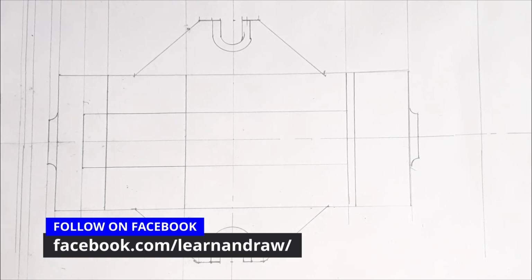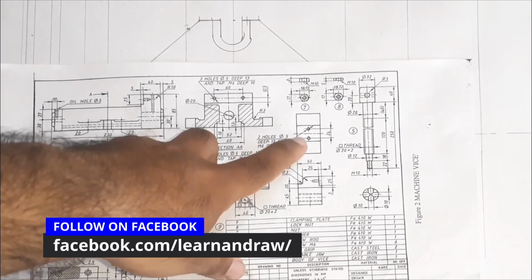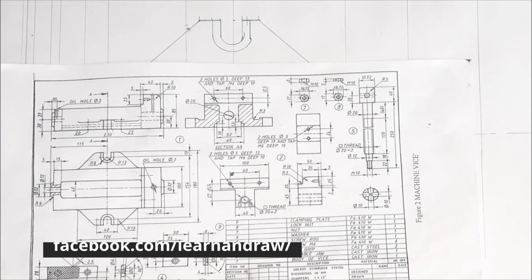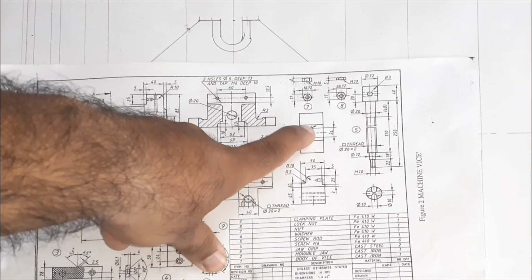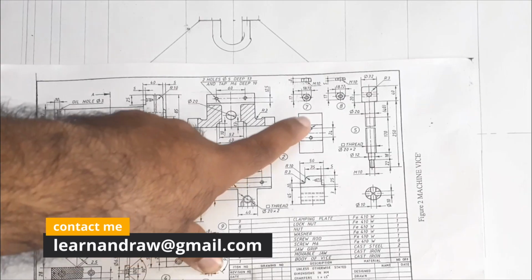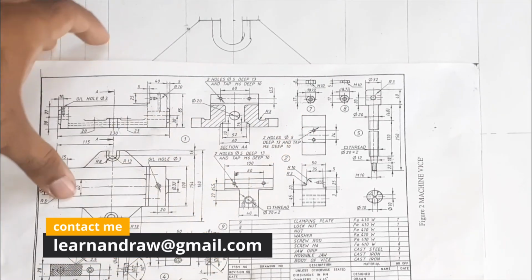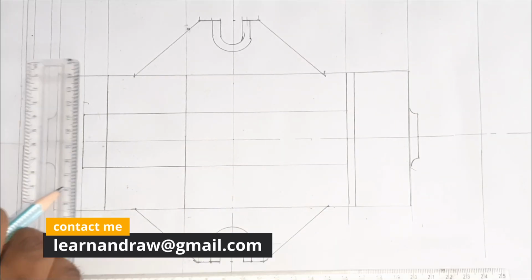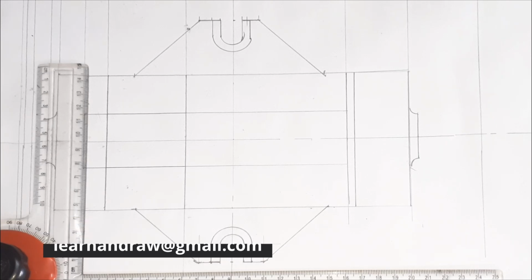Next step is we have to draw two holes. You can see these two holes will come from part number 8, that is the clamping plate. They are 24 mm apart from the axis line, 12 mm and 12 mm. They have a hole diameter of 5. So let's draw this one. Here we have to draw this at the center.